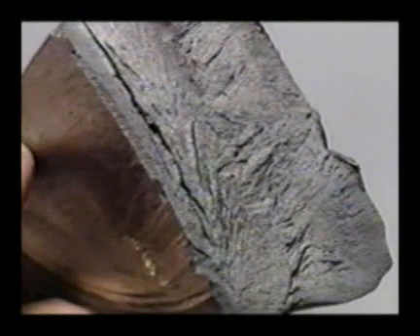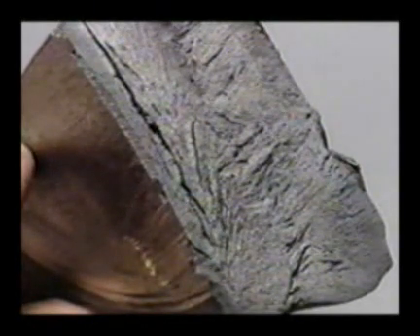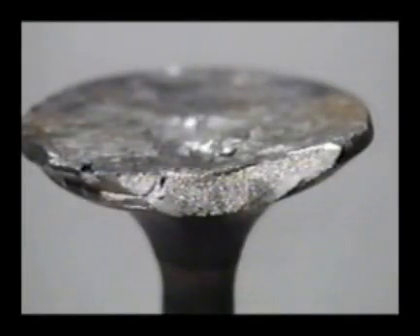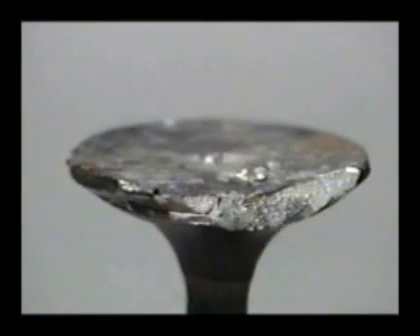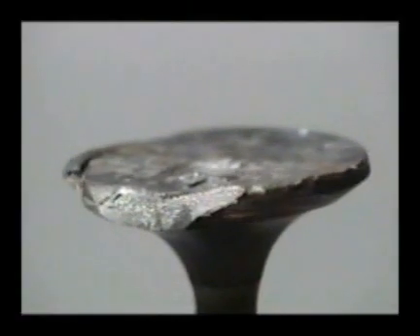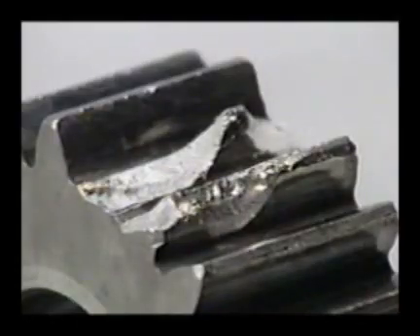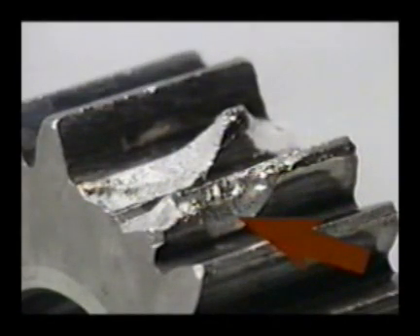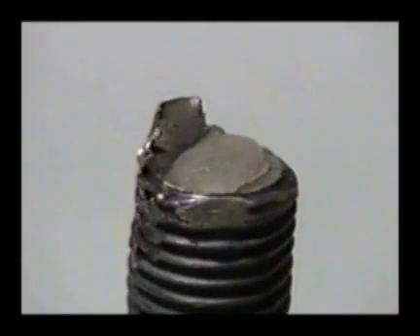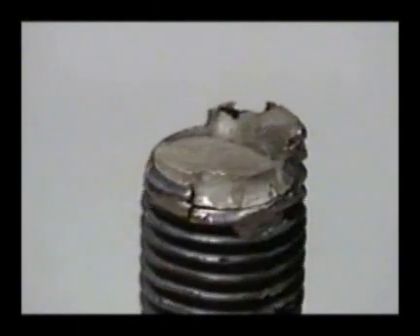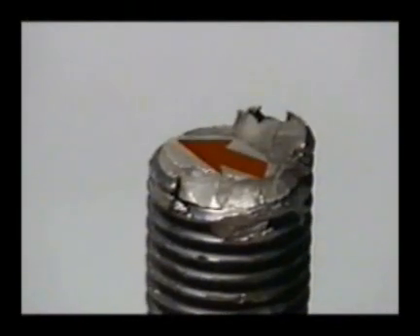In softer metals, brittle fracture usually produces these chevrons, while in harder metals, brittle fracture usually produces a sparkly, crystalline appearance without chevrons. It is much more difficult to locate the initiation sites of sparkly fractures since there are no chevrons to guide us. Sometimes the initiation site can be located by looking for surface damage, such as a nick or dent where an impact load was applied. Frequently, the fracture changes from brittle to ductile and leaves a shear lip at the final fracture. We should then suspect the initiation site is opposite the final fracture.